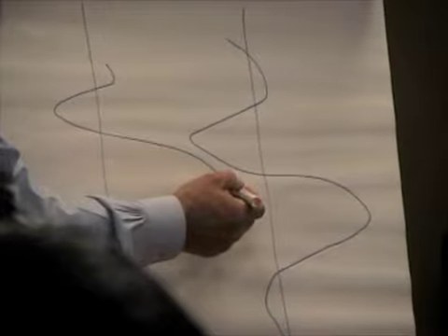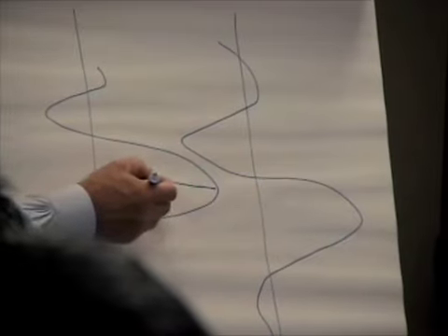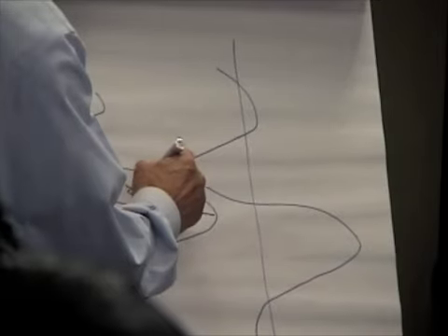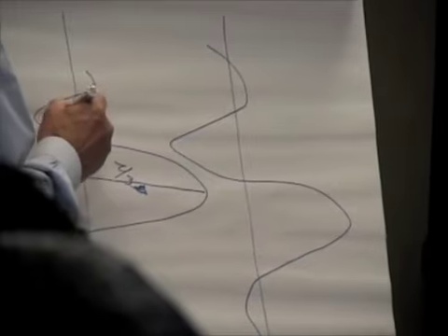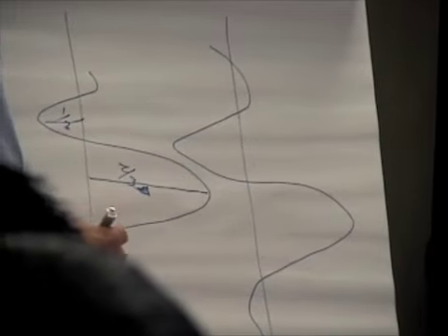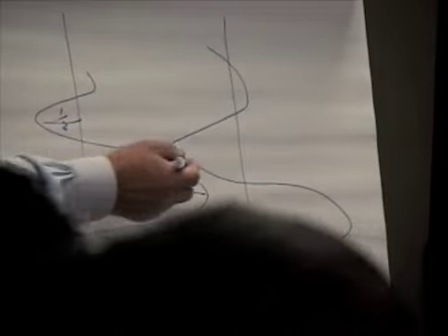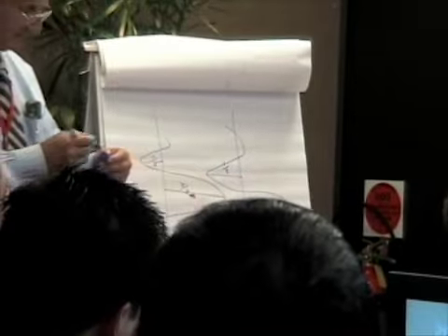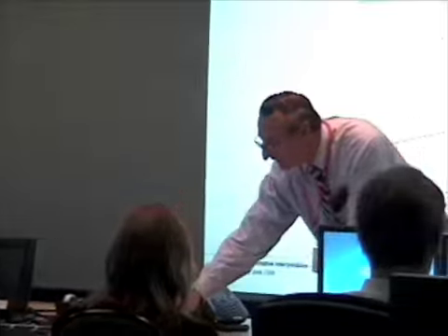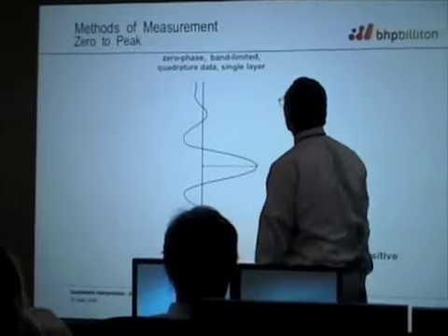And here we've got, say, 2/3 above the line and 1/3 each below the line, because we have zero DC. And if you square those, you don't get the same answer as 1/2 above and 1/2 below, which is what the 90-degree phase would be like. So the RMS of this is different than the RMS of that, but mildly different, 10% or something. So that's not very good. RMS is not really what you go for.